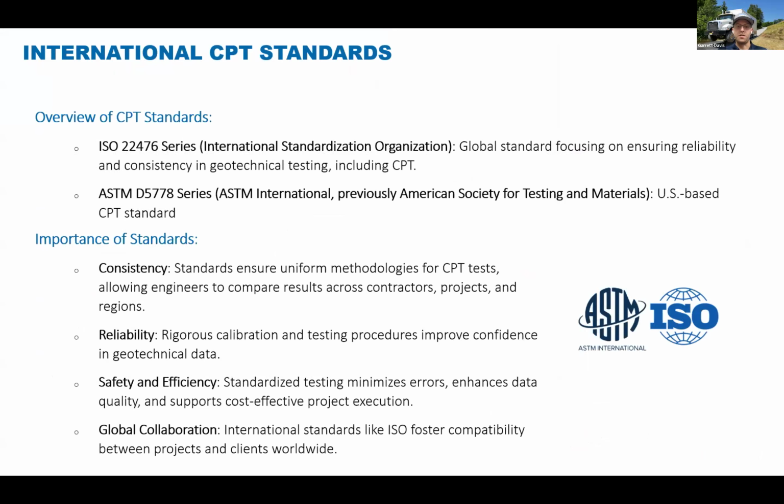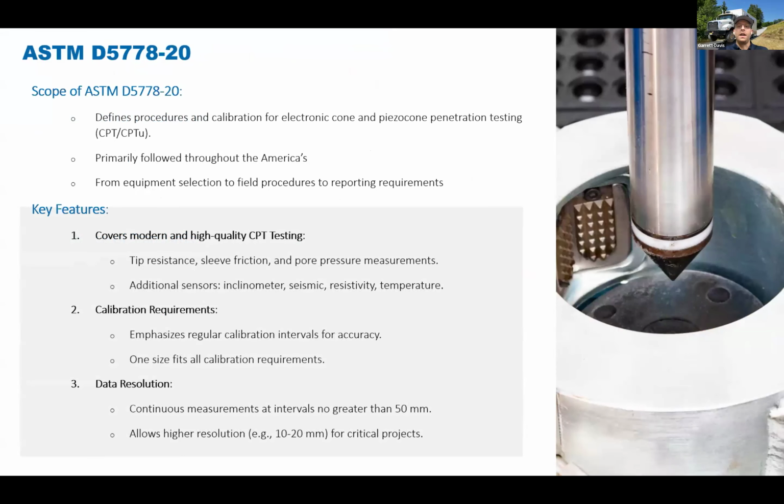So we'll just briefly touch on both of these. Among other aspects, the ASTM standard defines the lowest acceptable resolution of data, or 1 data point every 5 centimeters. At ConeTec, we collect at a standard rate of 2.5 centimeters, and there are smaller intervals available if higher resolution is required, down to a data point every centimeter or less.